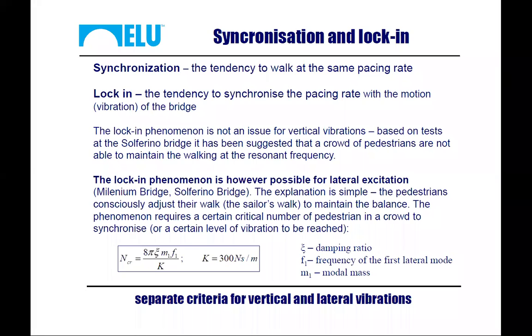Now, the lock-in phenomenon is very, very dangerous. And since you have gone through the course on structural dynamics, you will realize immediately why, because the lock-in will generate very high amplitudes on the bridge. It will generate resonance, and with resonance follow very large amplitudes of the bridge motion.